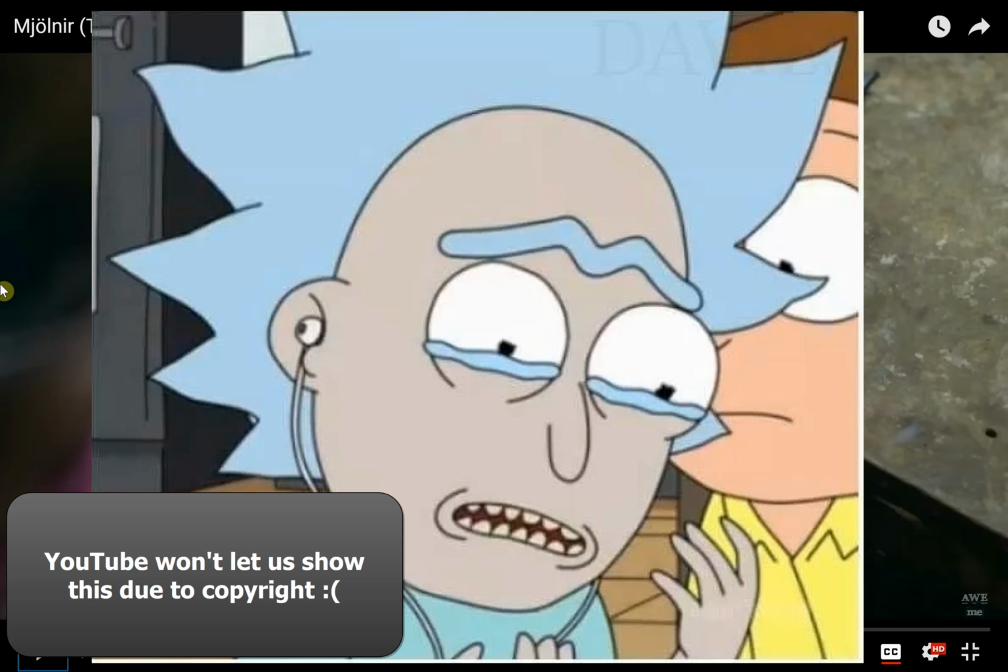Deformation. You're definitely deforming it. Why is it the case, if you've got a sheet of metal and you scrape that surface, in this case they sort of grind it down a little bit, that they're able to bend it right on that spot? Yeah, so surface flaws typically have to do with fracture, where the crack propagates. These aren't really brittle materials, they're ductile, so that's not exactly it. So what else is going on there? Why does it help you bend it in a nice straight line when you score that surface?